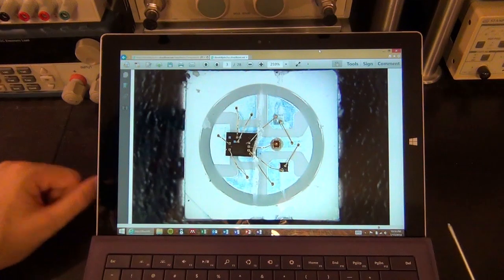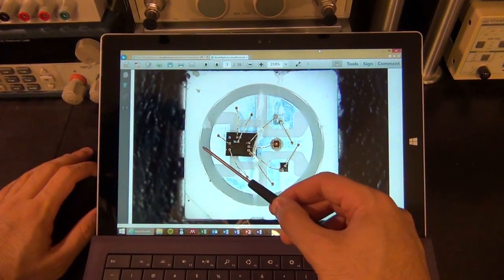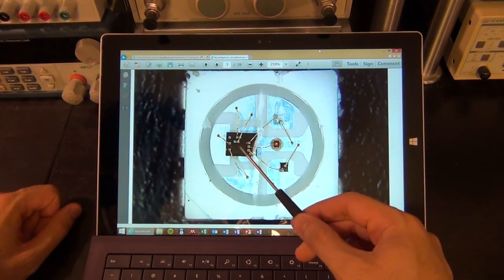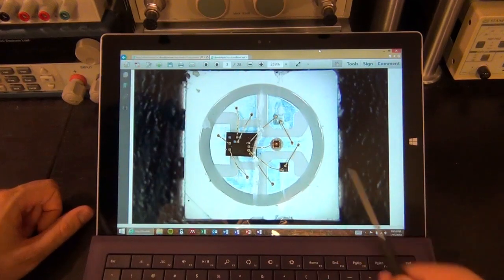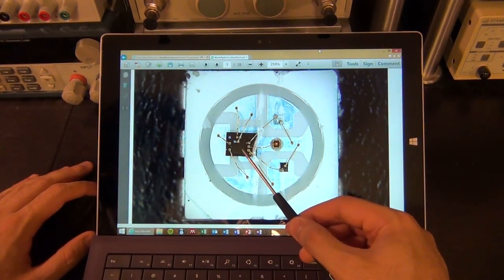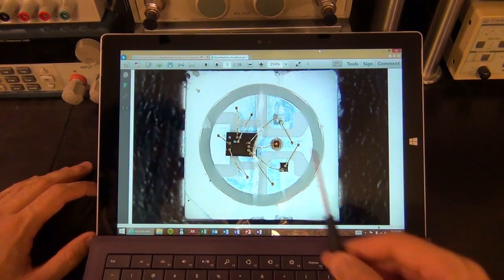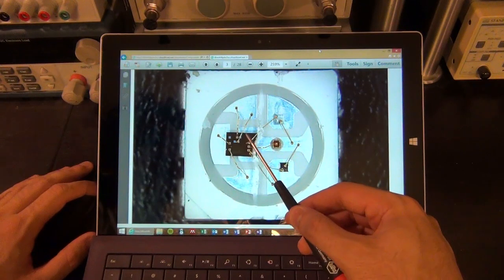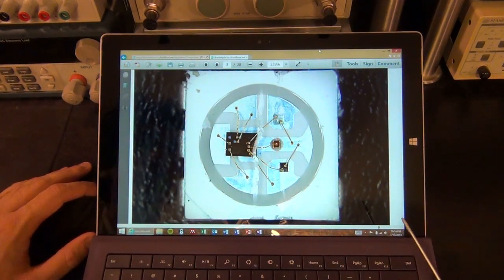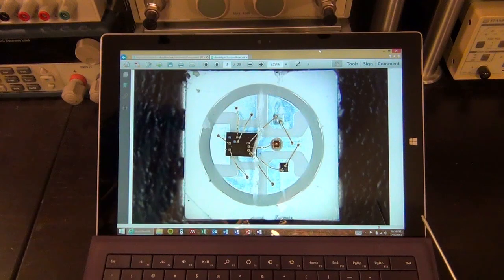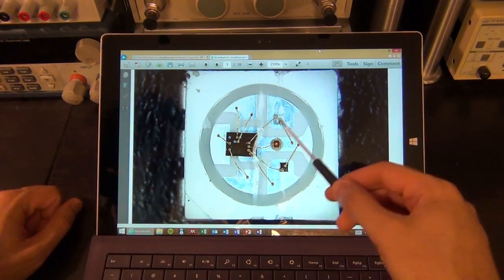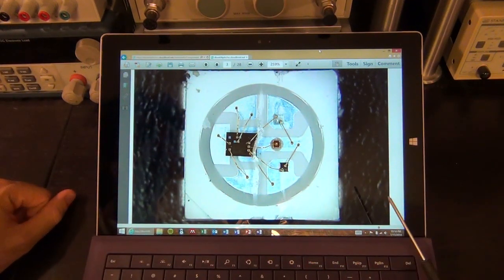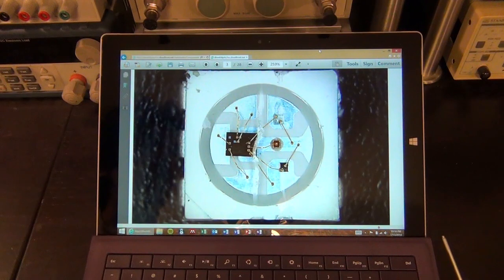So this IC does 2 things. It receives serial data, and once the serial data is completely received, it decodes it. Based on the timing information, because it's only one wire, there's no clock, so you're only giving it a single stream, so it's asynchronous. That asynchronous data, depending on very strict timing requirements, is interpreted by the semiconductor. Then it decides what PWM it has to put on each of these individual LEDs, because it is expecting 24 bits of data, 8 bits per LED. And then it decides what PWM is appropriate to get the different brightness for each of the LEDs, which then mix together and create all kinds of colors.